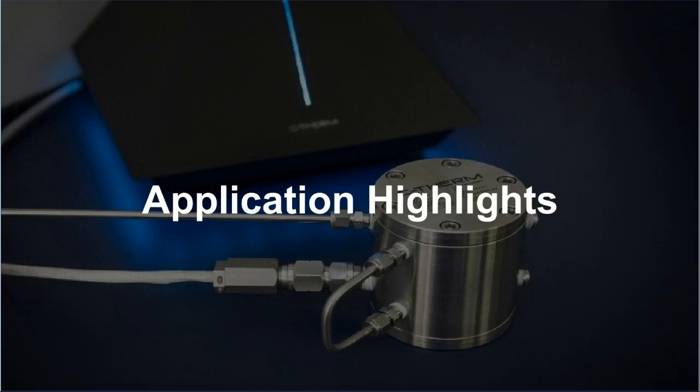These next slides will be going over some specific case examples, looking at different materials, whether it's solids or liquids involved in some of these processes, and looking at the effects of either temperature, pressure, or both on the sample matrix and how it affects the thermal properties, specifically thermal conductivity, and how that can give you valuable information, whether it's for designing your processes, modeling, or even using them as almost quality control methods to help screen the various materials that are coming off the various fractions or production lines.